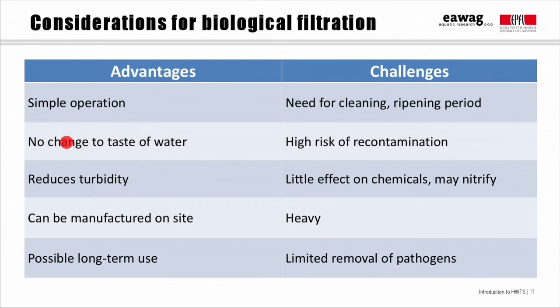The filter in general doesn't change the taste or the odor of the water, but it does leave filtered water with a high risk of recontamination, especially when safe storage isn't applied. Users really appreciate the great reductions in turbidity, but you should not expect that the filter has much of an effect on chemicals, except perhaps iron. And in fact, nitrogen might be made worse. Ammonia could be converted to nitrite.